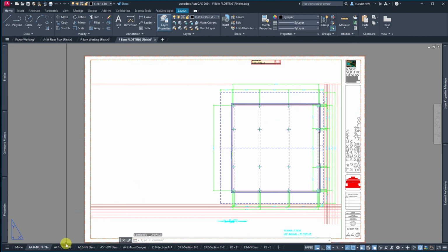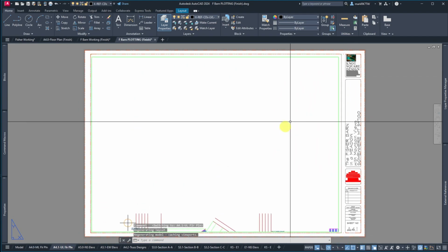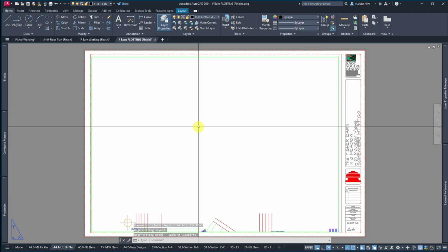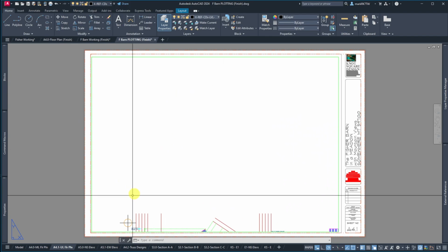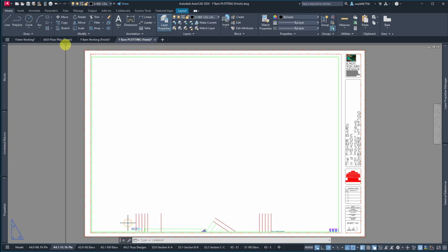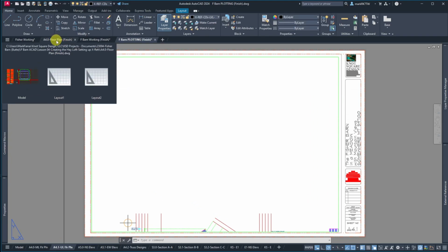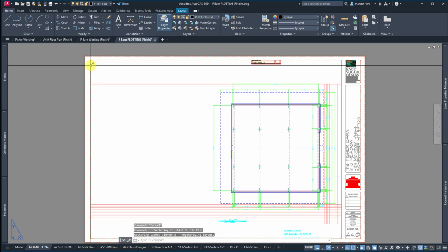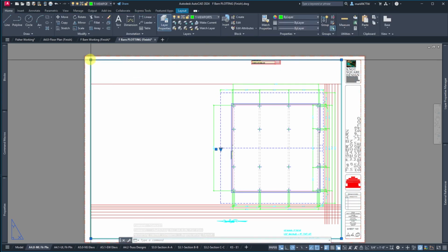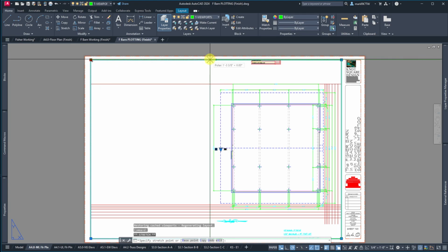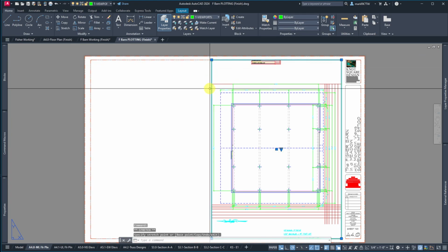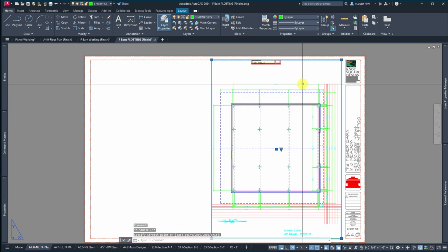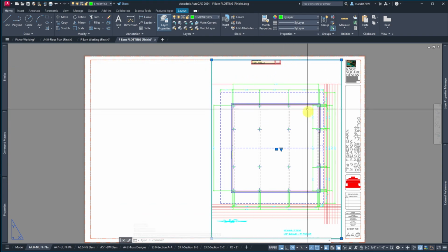What I had down here was another sheet that we could double click, and once we've created that upper level, we could bring it in here. But now that I've done the first and I know the size, because I had no idea, I drew something much bigger the first time around. Now that we've got something going, what I can do is take this viewport. I don't want to stretch my border, which is my printable border, just to outline my drawing and make it look nice. So I'm going to copy that over, or just move it over. And now that's my printable region.